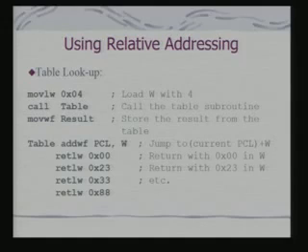Let us look at this example, and this is a very interesting example because it illustrates various features which you can use in PIC. Now, here we are using a table lookup, and this code is primarily for that purpose. Initially, you are loading the register W with 4, and then we are calling the subroutine table, and table would be referred to by the 11-bit offset. Okay.